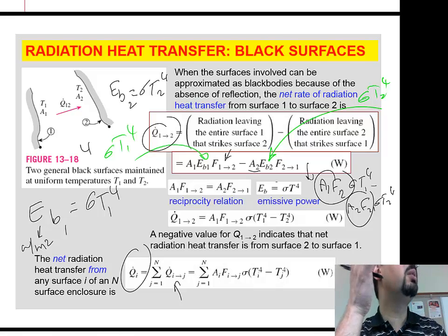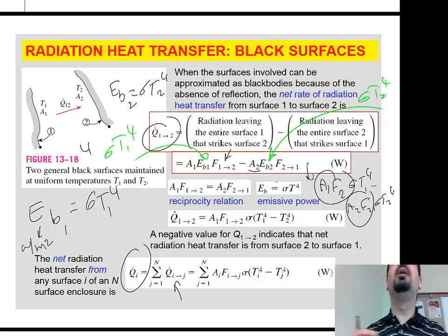Some of them will be plus, some of them will be minus. Say there's a flame here near the door, so I'm getting radiation from it, I'm getting hotter, and because I'm closer to the flame, I'm hotter than everyone else in the room. So I will start radiating to everyone because they are lower than my temperature. Okay? So at the end of the day, what's the Q that I'm getting by radiation? It will be the Q from the flame minus the Q to Jason, the Q to Lou, the Q to Jesse, and Q to everyone else in the room that I'm sending to. All right?